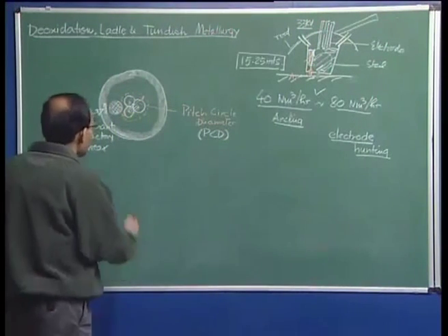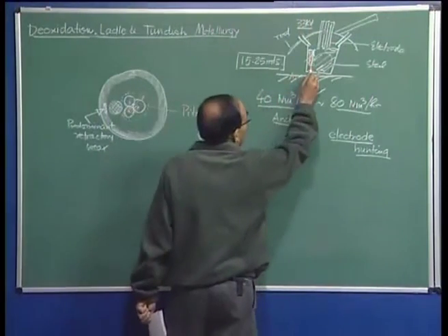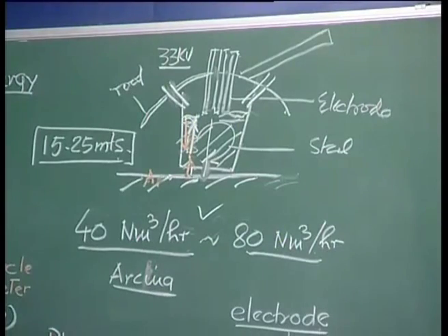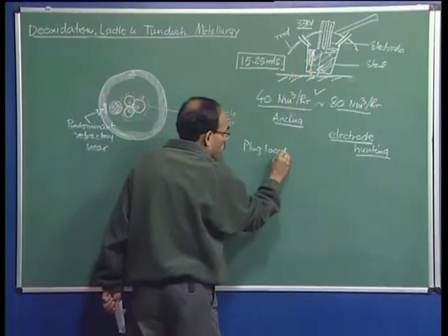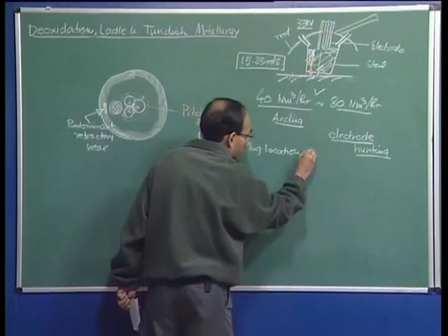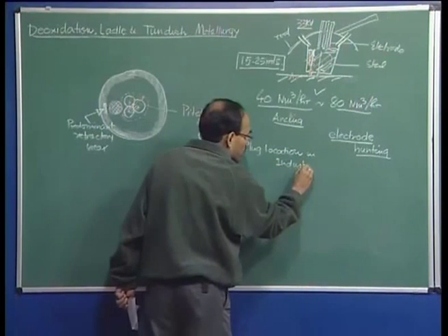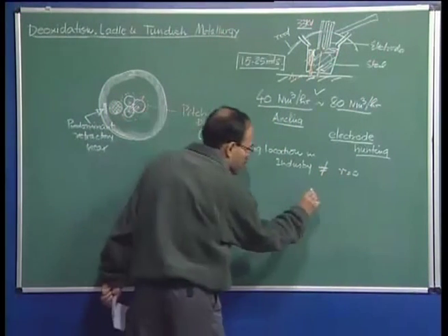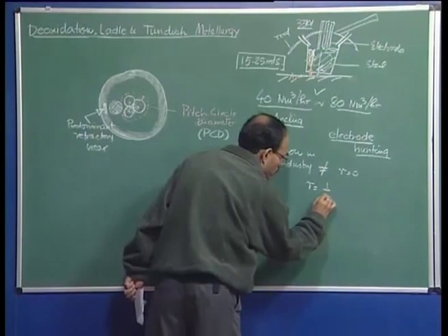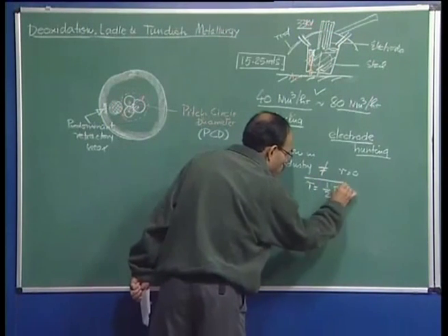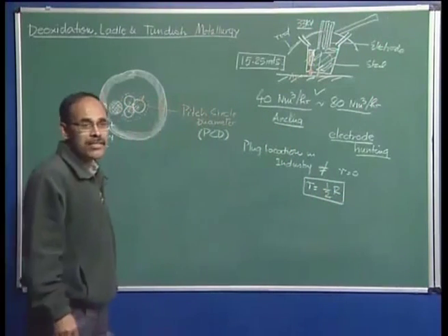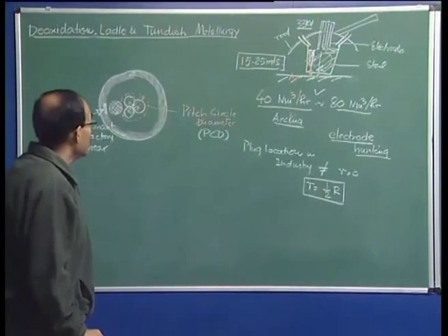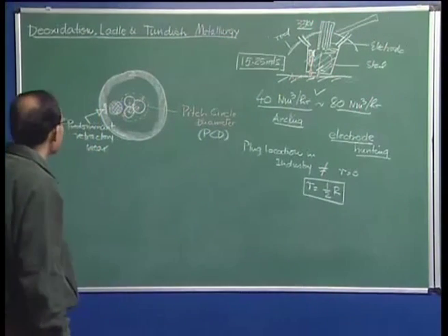significant. So, typical location, therefore, the location of the porous plug basically is at the mid bath radius position. So, the plug location in industry is not at r equal to 0, okay, but it is basically at the mid bath radius position. So, we will always do that. I think having said this much, let us now go to the other section of ladle metallurgy.